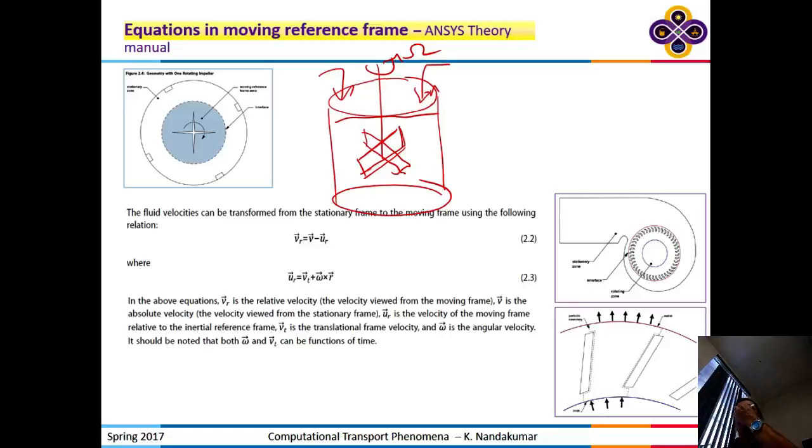Yeah. So in reality, when the impeller is moving, we have a pretty high swirl flow close to the impeller, and as we move more towards the wall we have most of the conditions. Whereas when we are modeling, it is the other way around. Right. That is in the moving reference frame. Yeah, how is that? I mean, does that affect? Is it the same? It is the same if you translate back to the laboratory coordinates.